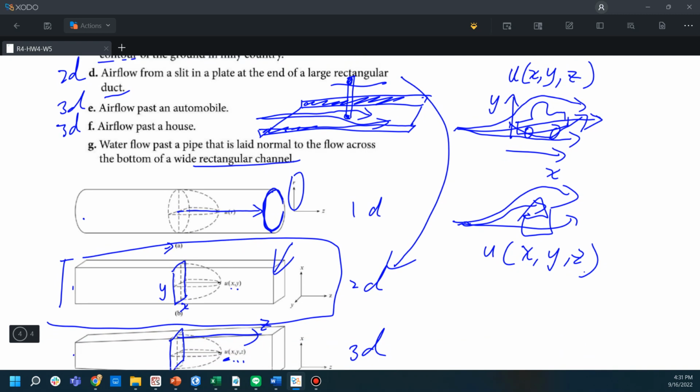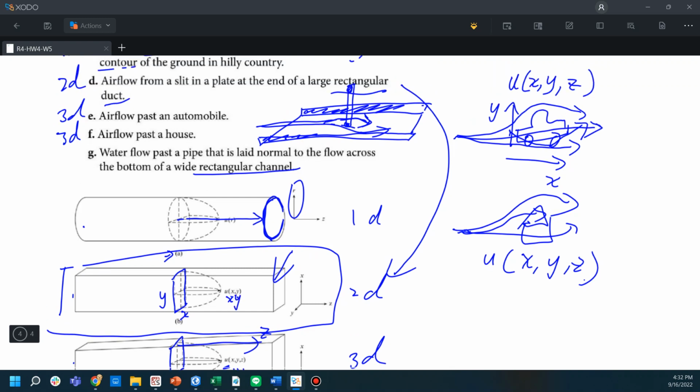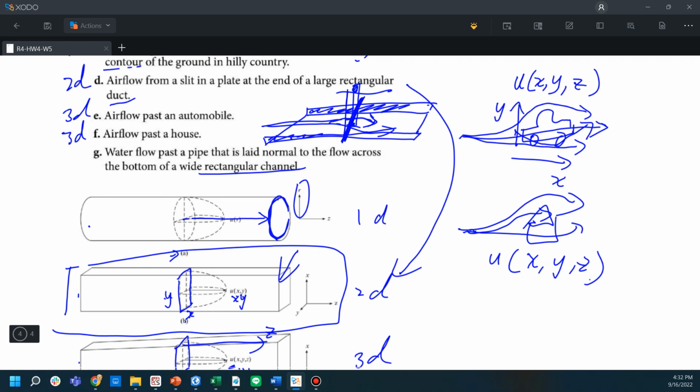So even though we have a pipe here and the flow rate changes here, everything can be described using x and y values, just to describe the locations, because we only care about the flow rates on this cross section that has a pipe. Okay, so if we see this statement like what we drew here, we can classify it as 2D.